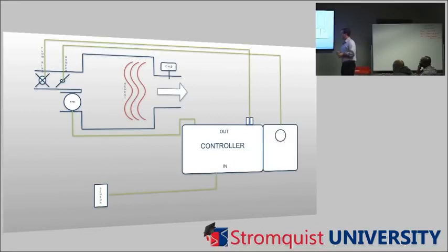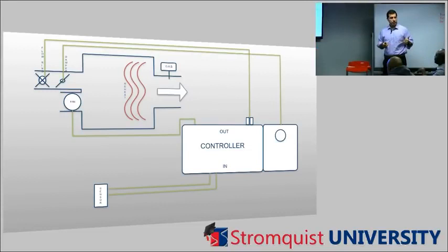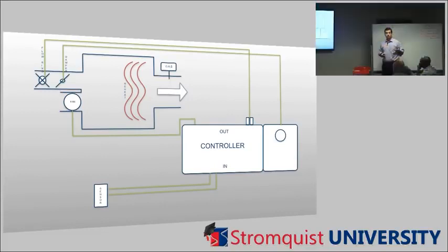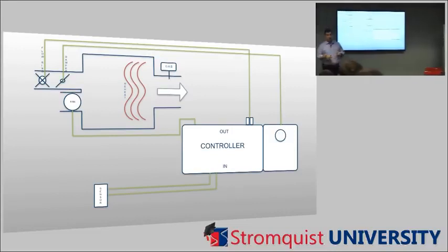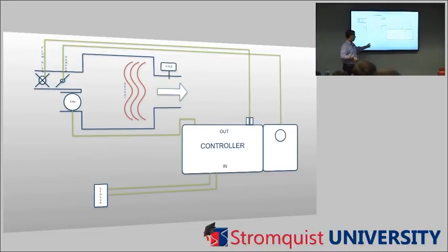So the sensor we've talked about is an input, but we're actually going to have two things. So the sensor's got to tell the controller two things. It's got to tell it the space temp in the space, and one other thing. Close. It's got to know something else, and I'm probably going to program this sensor. Space temp and then set point.